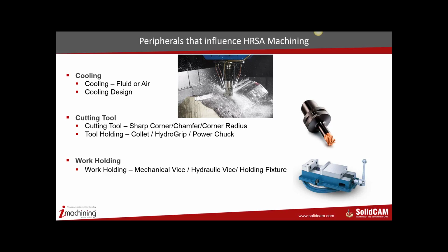The other important thing in the cutting tool is tool holding itself. Should we use collet? Should we use hydro grip? Should we use power chuck? Or should we use shrink fit tools? So we also need to make a very informed decision, and we are going to come to this in our next slides on what and how each one of them would make a difference.